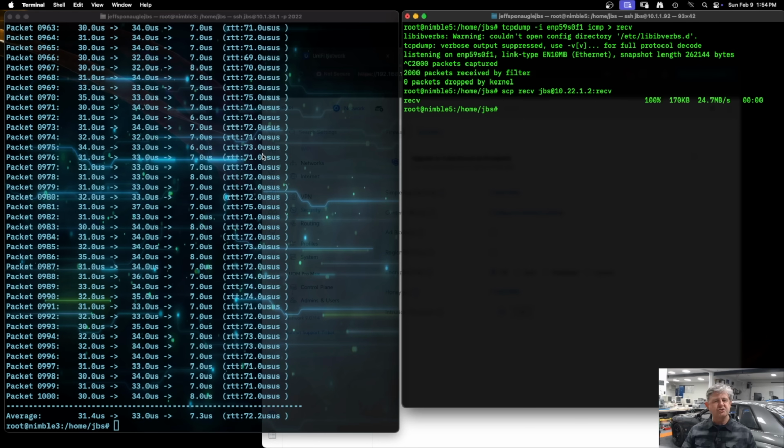So the clock synchronization certainly works. This is not going to give you accuracy of 100 nanoseconds or 10 nanoseconds, but in these microsecond ranges, I think it's reasonably accurate. For the devices we're talking about here, the more HOMELAB devices, I think this is a pretty neat way to measure latency. And the numbers were interesting. I wasn't sure what it was going to turn out to be, but 2 microseconds for a switch feels about right.